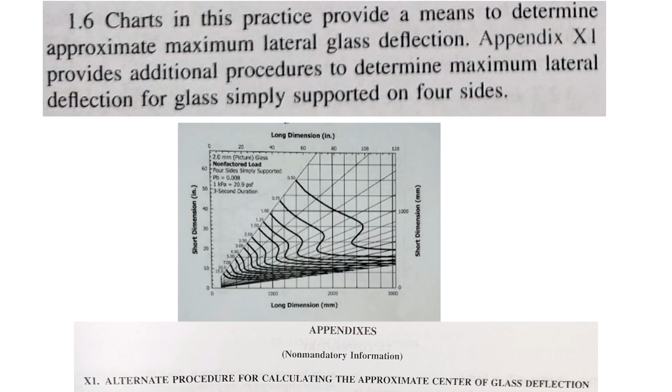Now this talks about lateral glass deflection, not necessarily load resistance. Those are actually two different things. On each one of those pages, there are two different charts. There's the load resistance one at the top, and then there's the actual glass deflection at the bottom.